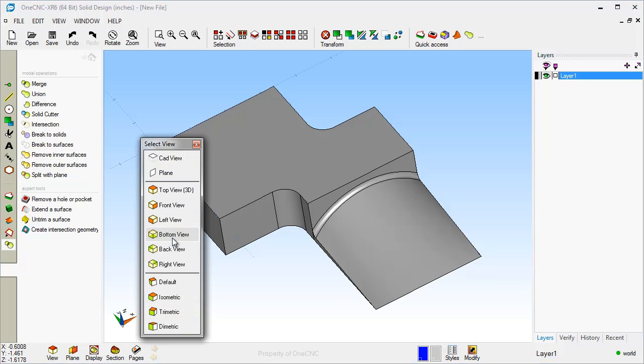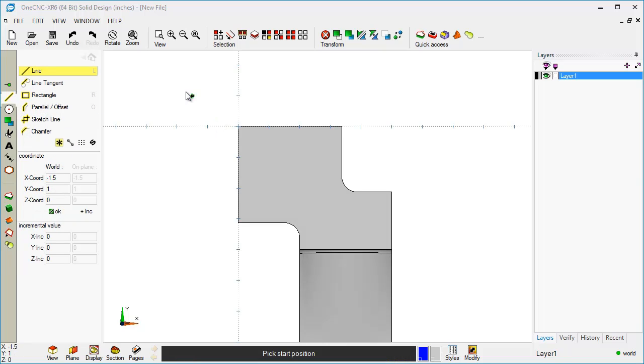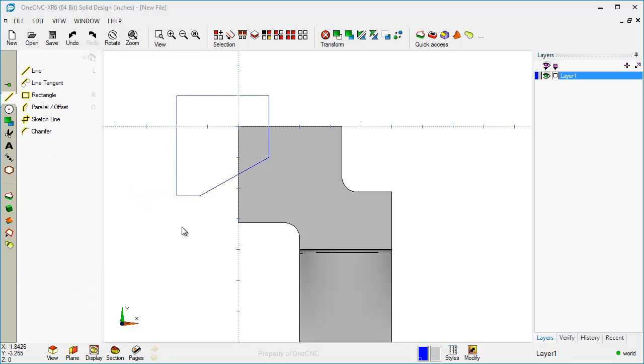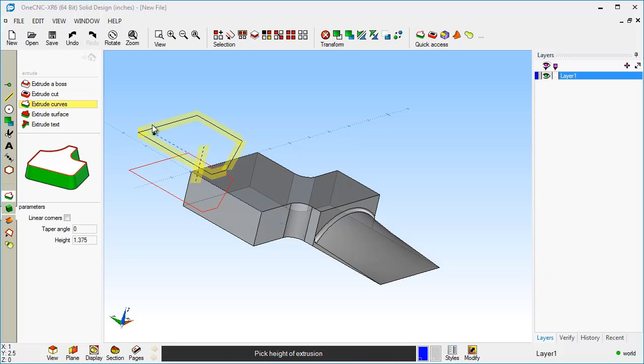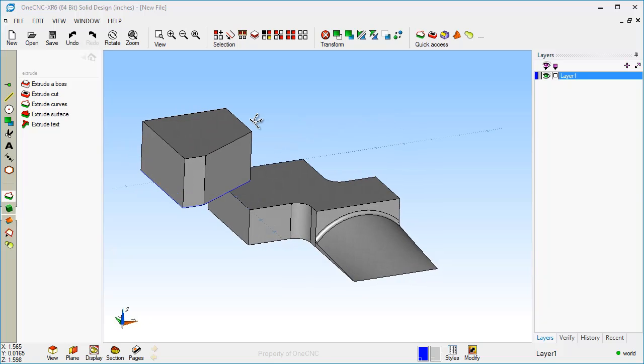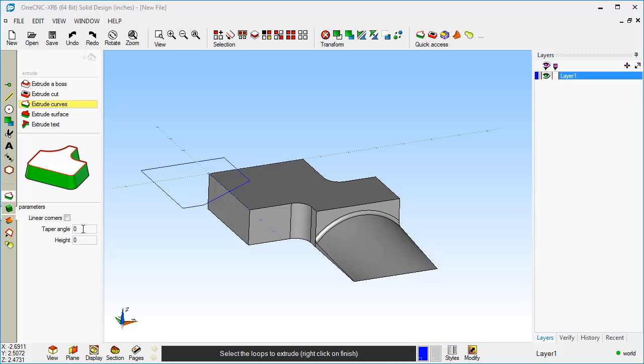Now, the difference tool provides the ability to subtract one solid model from another solid model. So the first thing I'm going to do is just quickly sketch a closed boundary. And of course you can use coordinate input, but I'm just using grid point snap just to quickly create a closed shape. What we're going to do now is use the extrude tool. I'm going to extrude that up. In fact, let's make this extrusion a little bit more interesting. I'm going to undo that, just hitting Control Z on the keyboard. And let's add a taper angle of, how about -12?